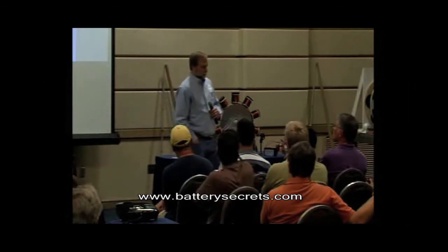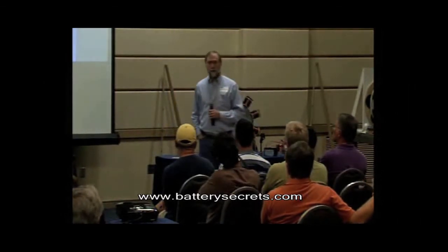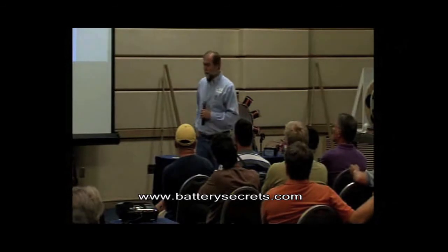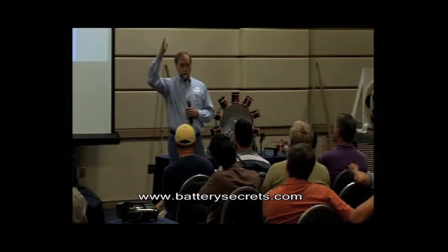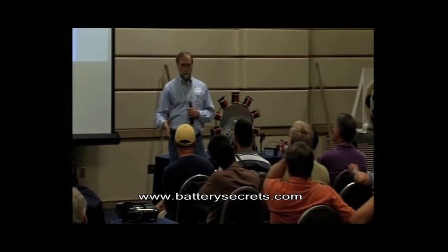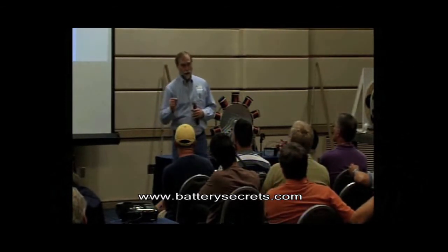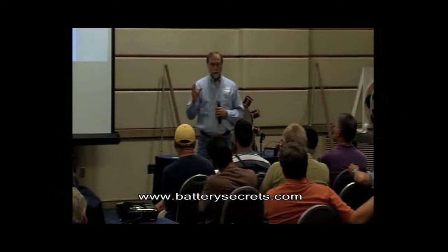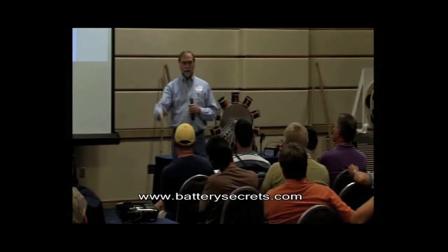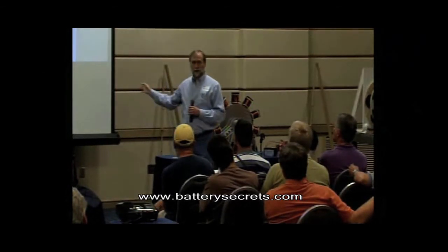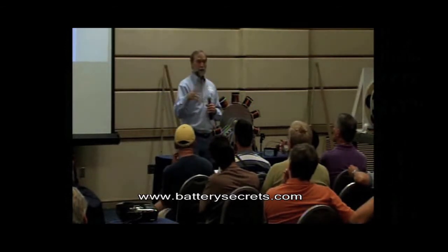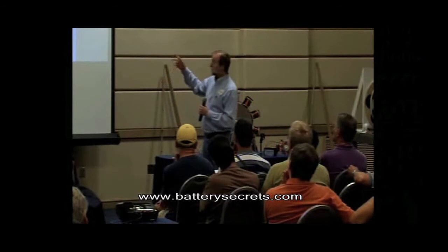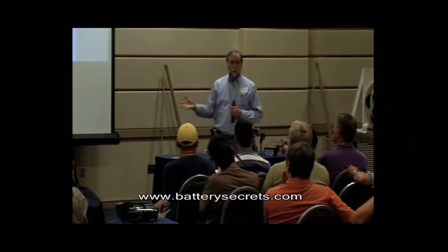Well, here's the thing. Would it give you more life? Well, you'd have to, quote, reform the battery. See, originally when they figured out how to make a battery, they just put 2 lead plates in sulfuric acid. And what would happen is that the sulfuric acid would attack both plates, creating lead sulfate on both plates.